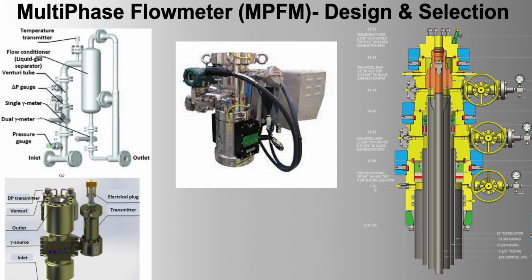3. Enhanced data quality. High-frequency data collection. Frequent data collection improves the quality of production data, aiding in more accurate reservoir management and production forecasting. Detailed flow analysis provides detailed insights into well performance, including identifying issues such as water breakthrough, gas coning, or slugging.